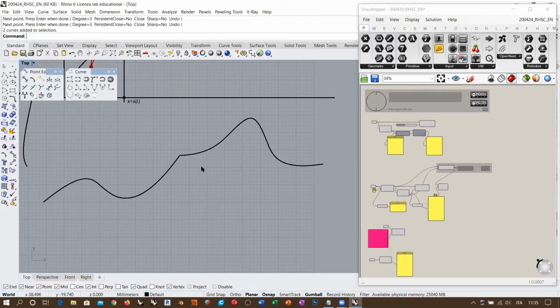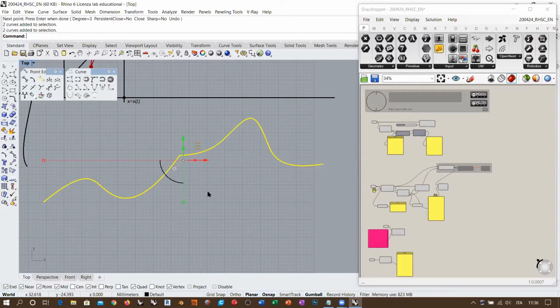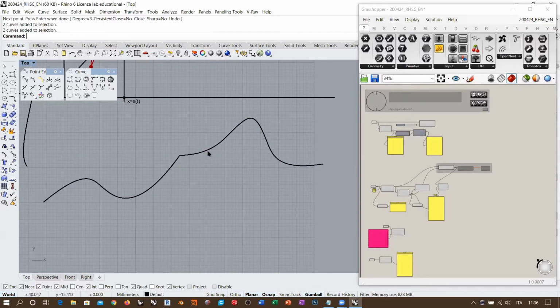But the average user, or also the professional in that case, tends to create that kind of object using a polysurface. So several surfaces connected together. And the thing is that you don't want creases, visible creases along the surfaces. You want the object to appear as smooth as possible. So one thing is talking about continuity, and one thing is talking about smoothness. We don't want just continuity in Rhino. We also want smoothness. So this is continuity already, but it is not a smooth continuity.